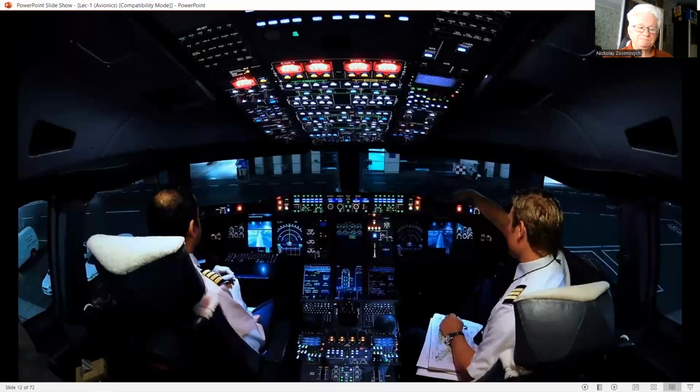A major driver in the development and introduction of avionics systems has been the need to meet the mission requirements with the minimum flight crew. In the case of modern civil airliners, this means a crew of two only, namely the first pilot or captain and the second pilot. This is only made possible by reducing the crew workload, by automating the tasks which used to be carried out by the navigator and flight engineer.